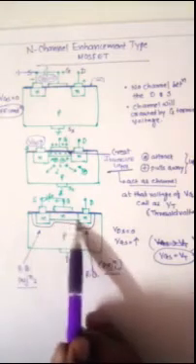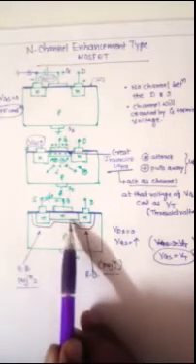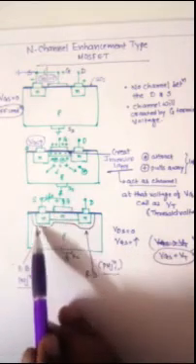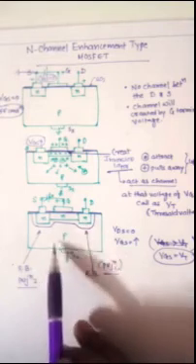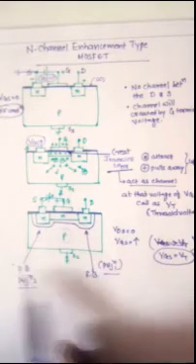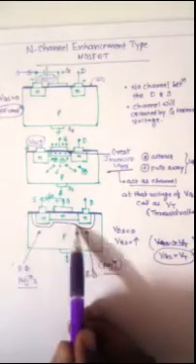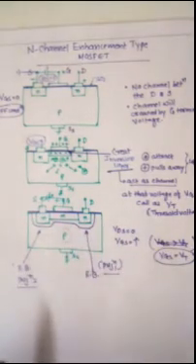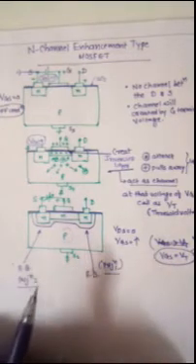at the value of VGS creates the channel. This is created by the electrons, so here it is N type. This way we create the channel. Now VGS is increasing. Here is the N type material, and with respect to the P type material it makes a junction. Here we show the reverse biased junction, so the depletion width is created. This way we consider that when the voltage is not given, it is in the off condition, and when the voltage is given, the channel will be created.